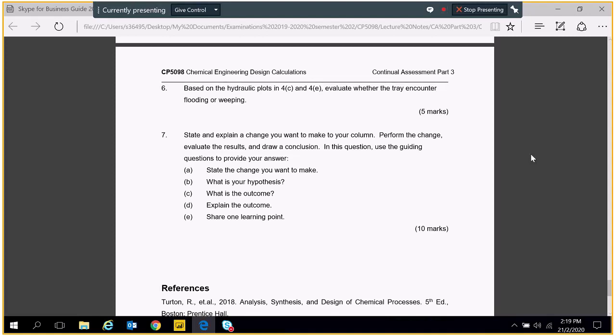My hypothesis is that if I increase the purity of the benzene from 96 mole percent to 98 mole percent, the reboiler duty will increase because now there will be more liquid, for example, and the condenser heat duty will also increase, assuming that you keep the same number of stages. So assuming now you have 19 or 20 stages, you keep that.